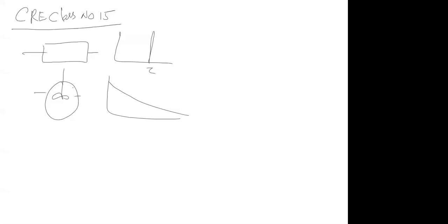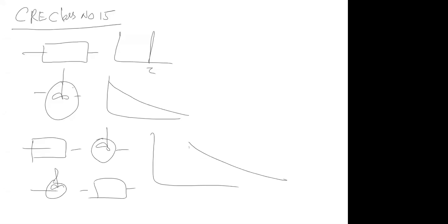So we'll recap for a minute. What is PFR RTD? It is a single straight line at tau. What is CSTR RTD? It is this kind. So CSTR followed by PFR is this kind of RTD. PFR followed by CSTR, the RTDs are something like this. They will start at a time of PFR. At what time will it start?